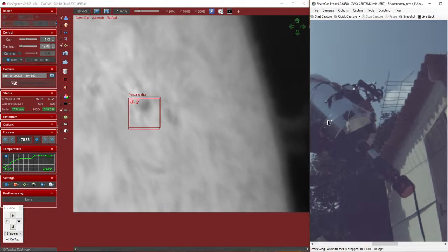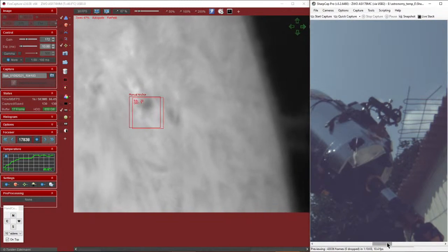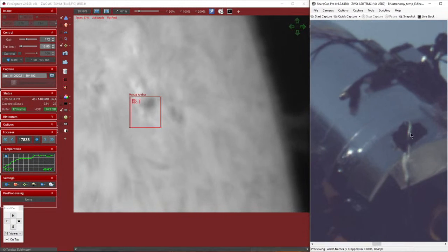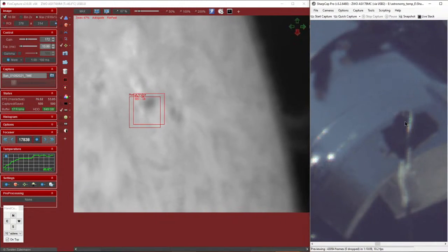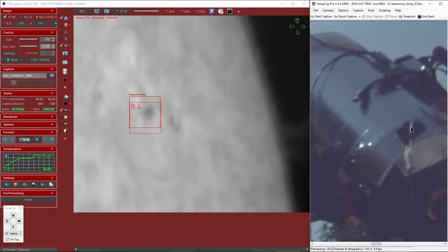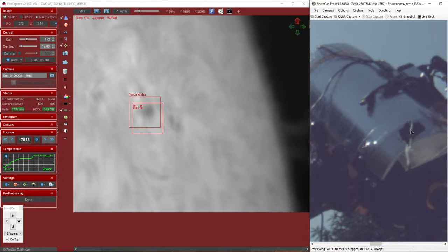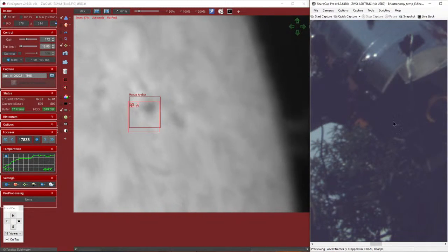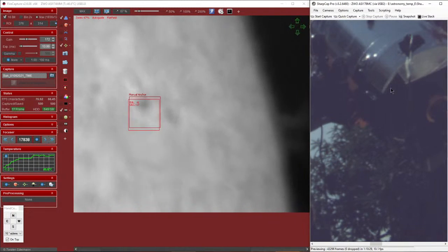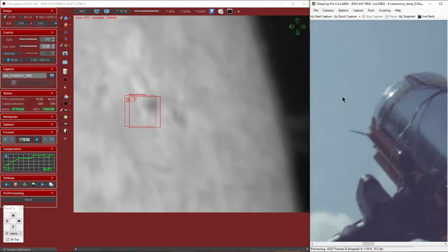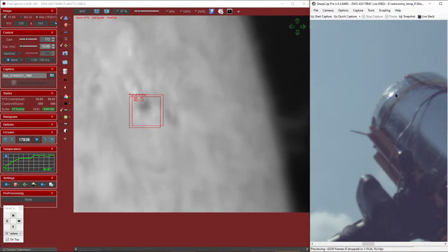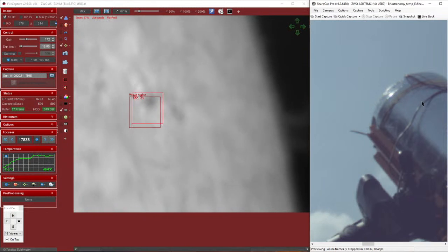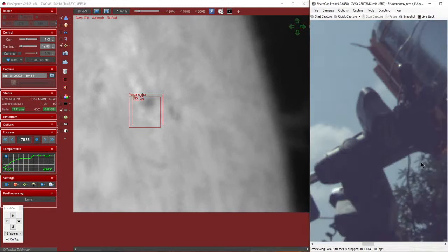So there are actually a couple of cooling systems. One is just these fans. This cable goes inside the scope, and there's one fan pushing air from here, and one on the other side, which you can't see from here, that is pulling air. So it creates this circulation of air inside the scope behind the mirror. So that's one. Another one is here, which is another small fan on top of a Peltier, which also actively cools the secondary mirror.